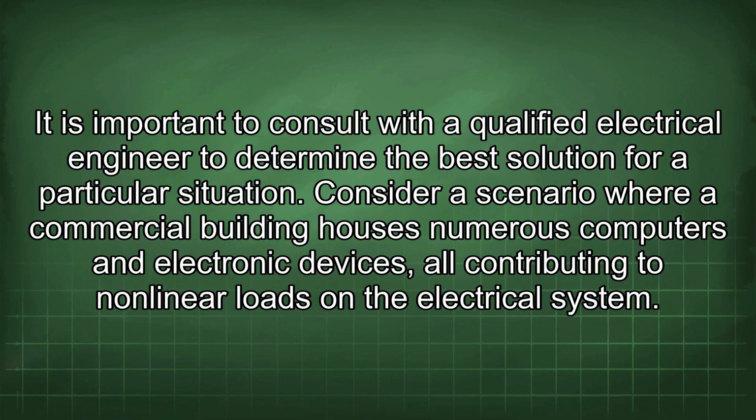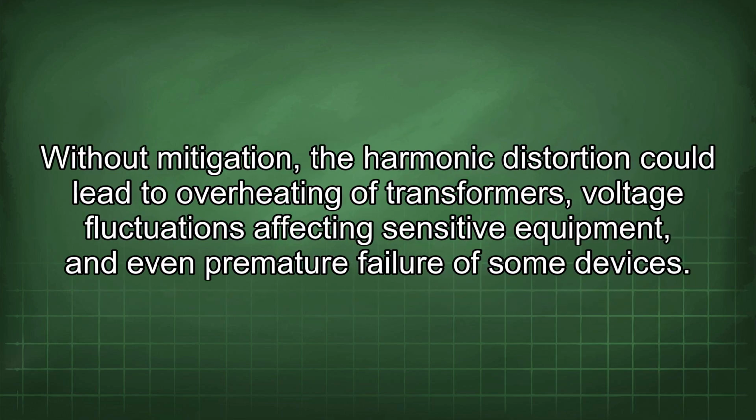Consider a scenario where a commercial building houses numerous computers and electronic devices, all contributing to nonlinear loads on the electrical system. Without mitigation, the harmonic distortion could lead to overheating of transformers, voltage fluctuations affecting sensitive equipment, and even premature failure of some devices.